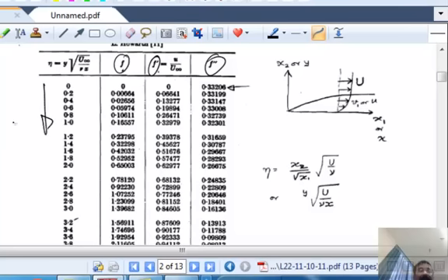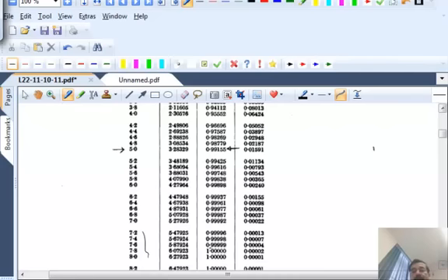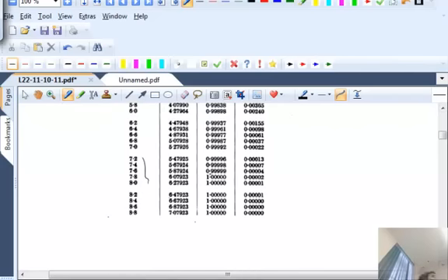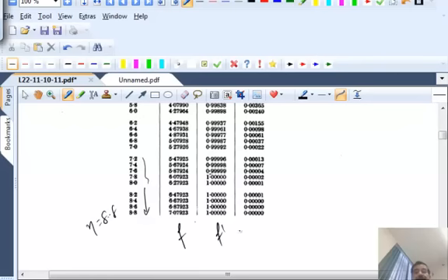So this is your independent variable eta, going from 0 all the way to infinity. But infinity is just a concept. So in this case, you find that numerically when you integrate, if you reach eta of 8, you already have reached the edge of the boundary layer. How do I know from this table? I made the statement that if I reach the eta value of about 8.8 in this table, that is the edge of the boundary layer. It's as if I've gone to infinity. What in the table makes me state that? Remember, this is f prime, this is f double prime. Now, what is f prime?